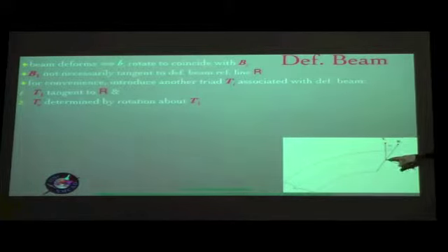Now you would have B3 along this, but instead you would have T3 perpendicular to T1, because just like the big B system, that big T system is also orthonormal. In other words, all these vectors are mutually perpendicular to each other. Now the difference between this T3 and B3 is basically your transverse shear.